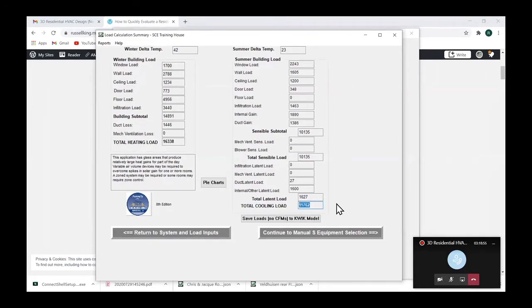You want to make sure that the sensible capacity meets the sensible load, and the latent capacity meets the latent load. You don't want to make sure the totals match the totals, okay? Because there are different kinds of cooling. That's an all-day topic, talking about sensible load, latent load, and all that other stuff. So do a little additional research on that. Take my word for it at this point, but you're going to want to pick an air conditioner that meets this sensible, and then check the latent capacity of your air conditioner and make sure it provides at least this much latent capacity.